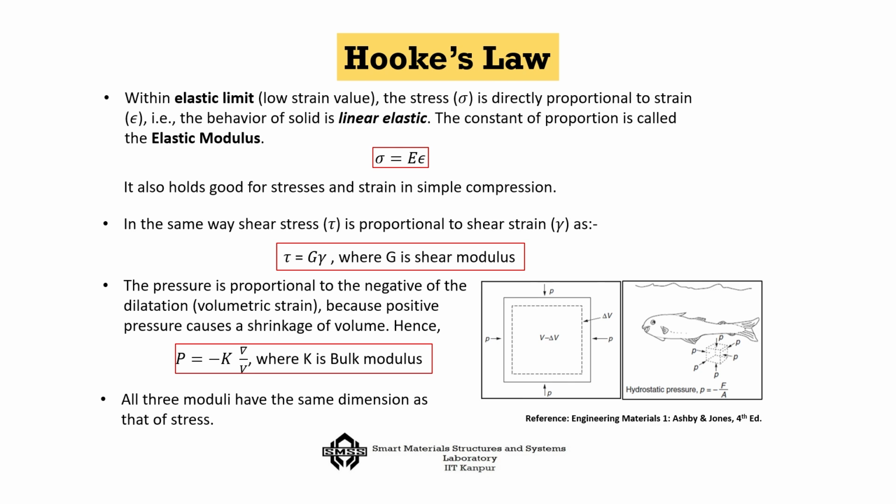And now, let us take a look back at our Hooke's law. Okay. For an axial case, we know sigma equals E epsilon. So, that is how we always use the modulus of elasticity E, the Young's modulus. And then for shear case, we have tau equals G gamma, and for the volumetric case, we have the pressure part that now comes into picture.